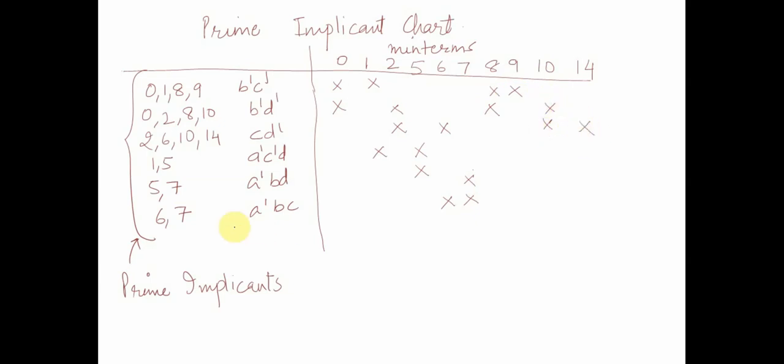Now what we have done is we took the initial minterms and mentioned them on the x-axis. This is the initial function we had, and these are all the prime implicants, the terms we got by circuit minimization. We can minimize this circuit further, and to do that we created a prime implicant chart. Now we have to look for minterms that are covered by a single term only.